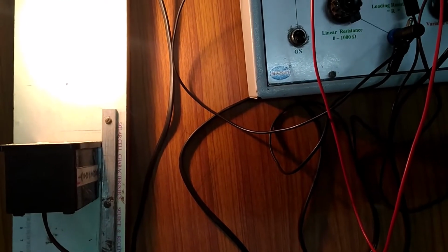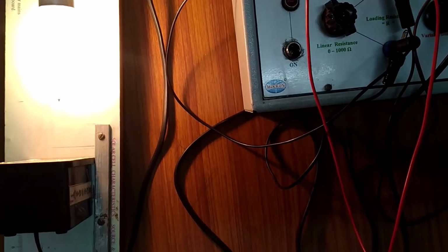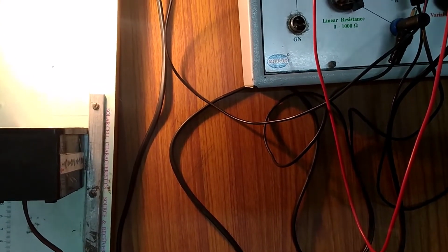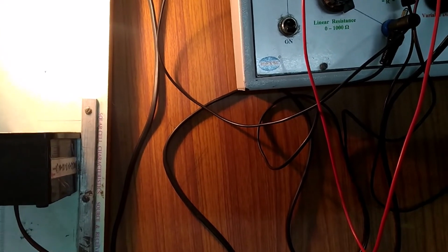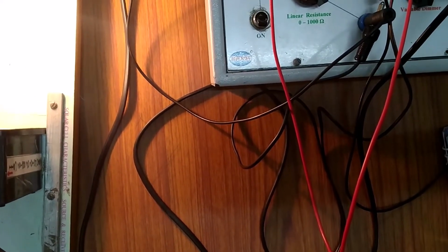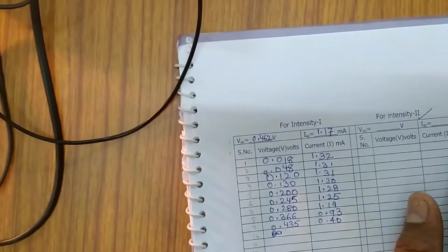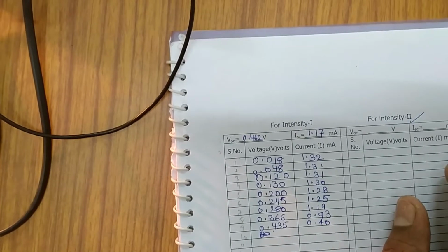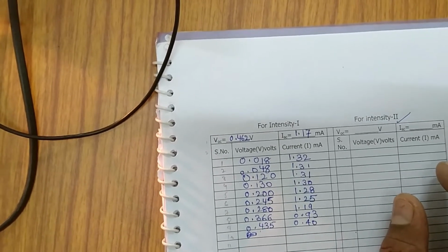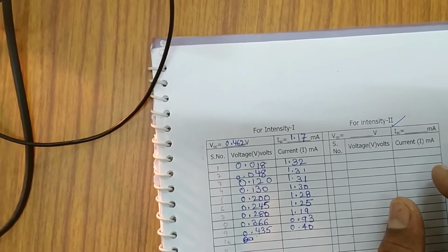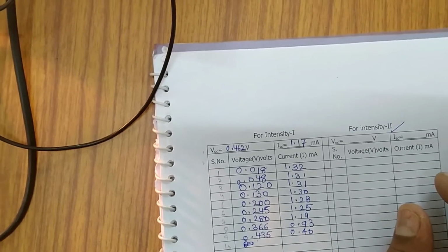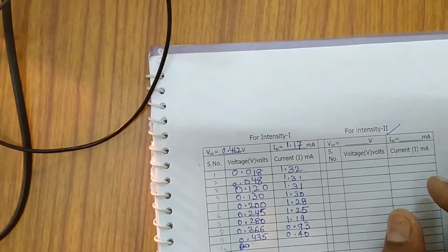Because while calculating the efficiency of the solar cell, we take the solar constant as a constant, which is taken as the power received on the earth perpendicular to the direction of sun per unit area, and that will be calculated under different atmospheric conditions called AM0, AM1, AM1.5, etc. They do this calculation of solar constant over a period, through different seasons and different weather conditions, and they found out what is the constant. That constant will be taken in the calculations.